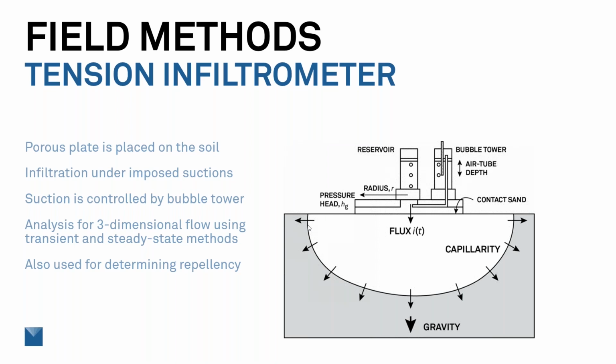What's really nice about tension infiltrometers as well is, again, there are approaches available to determine repellency as well. And so if you're doing post-fire work and you're trying to understand how hydrophobic the soil is after a forest fire, or if you're just interested in hydrophobicity in general, these can be really useful tools for trying to make that estimate.